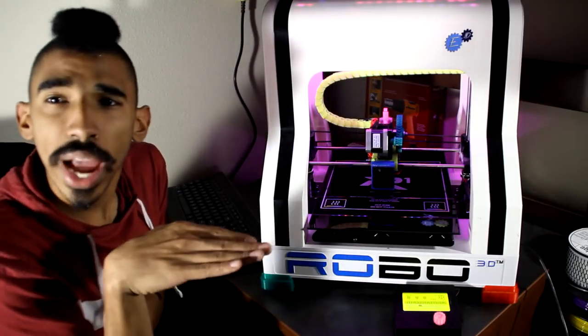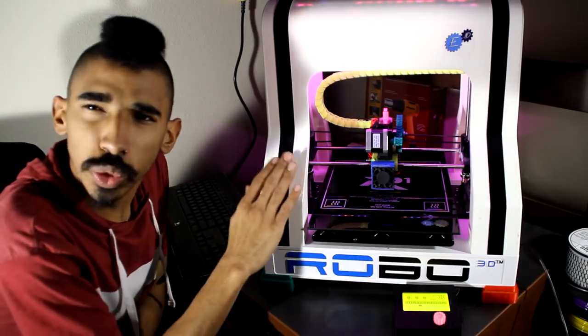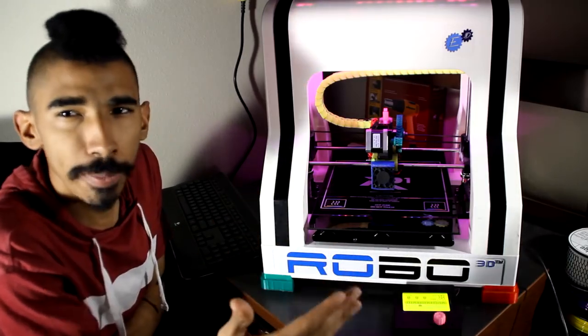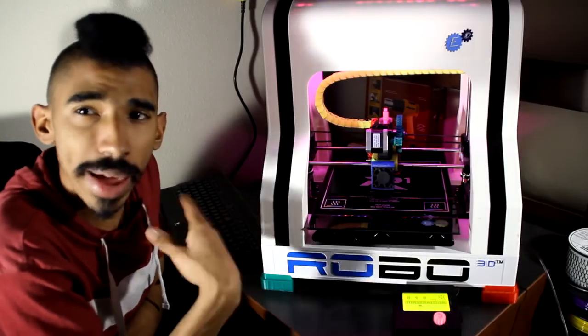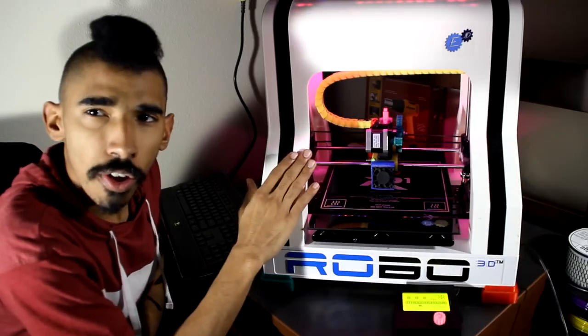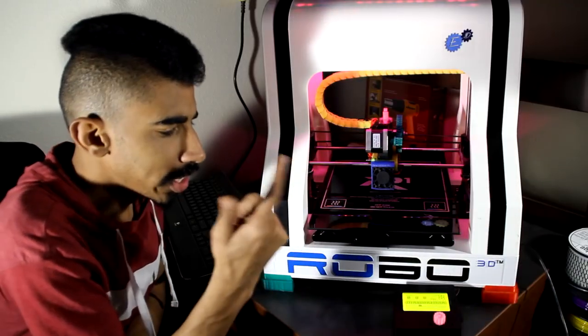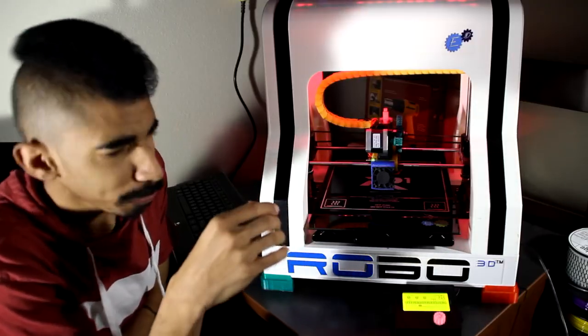All these commands are waiting in the cache of the 3D printer. Currently it's waiting till it gets to the temperature before it implements the commands. So I just sent all the commands to the printer, but it won't implement any of them because it's waiting for the temperature of the extruder to get to 220. It's currently at 190 right now, still heating up.